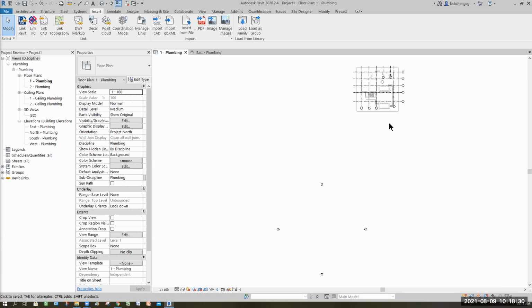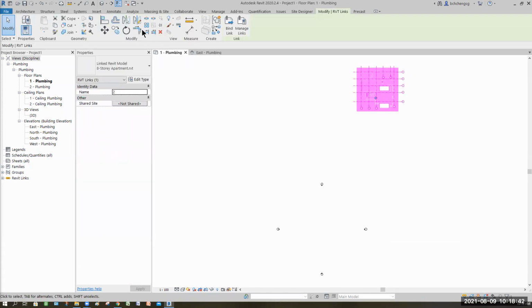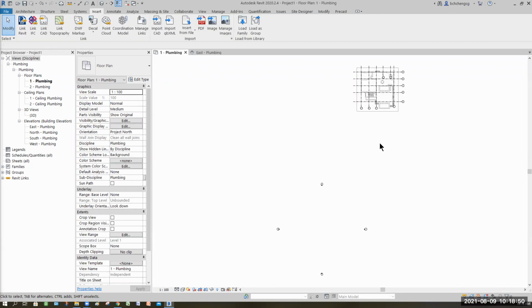Temporarily, see, I cannot select them because I turned off my link. If you cannot select, remember, you need to uncheck the link, then you should be able to highlight back. So temporarily, you pin first in case you accidentally relocate it. These are the steps you must remember.